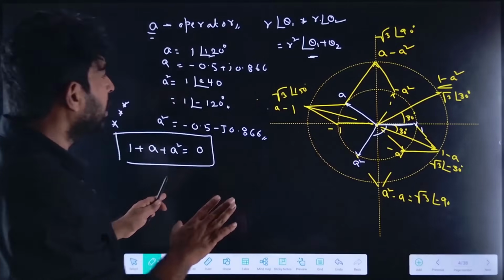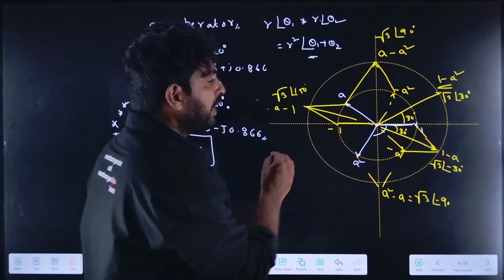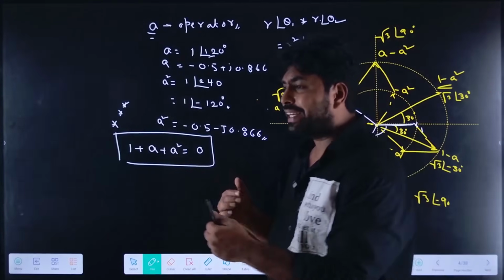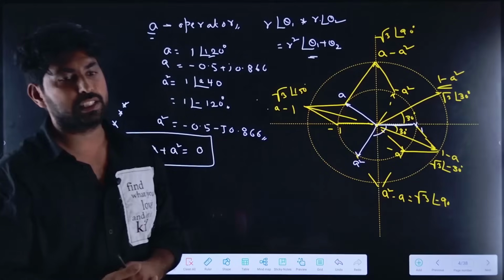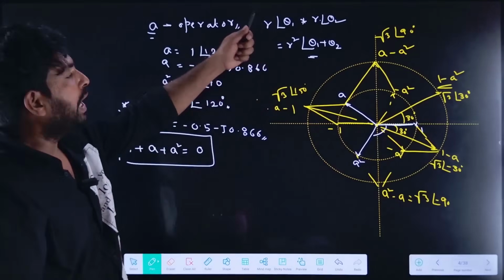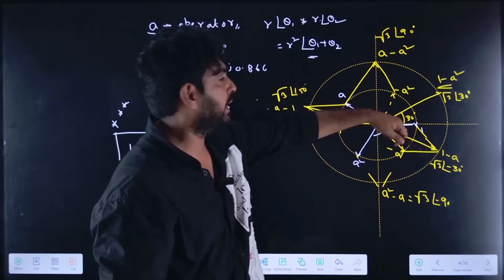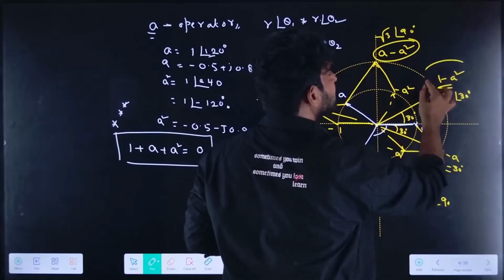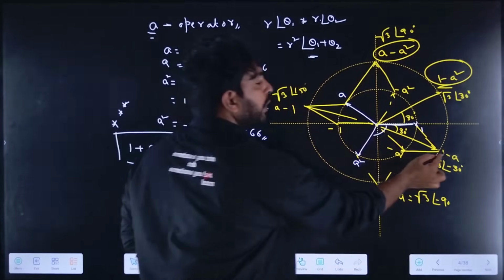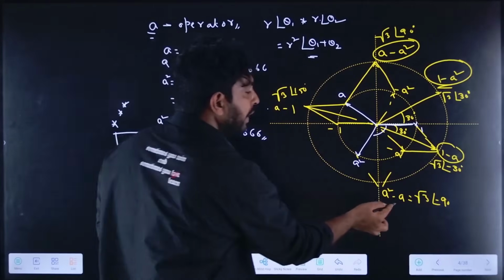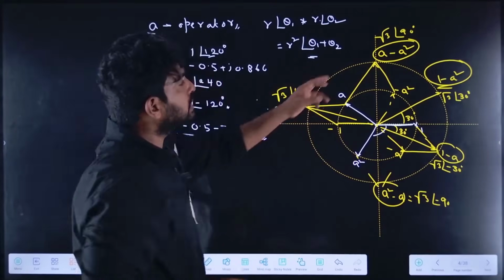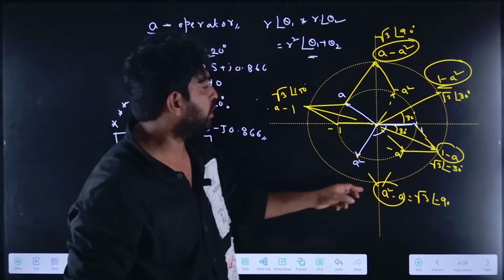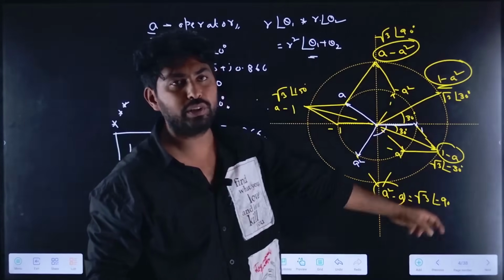Now it is very simple if you understand the operator here. This analysis is important to get easy calculations of three-phase systems, where a is an operator and a is 1 at an angle of 120 degrees. We have found 1 minus a square, 1 minus a, and a square minus a, and the upper circle will be in terms of root 3, right?